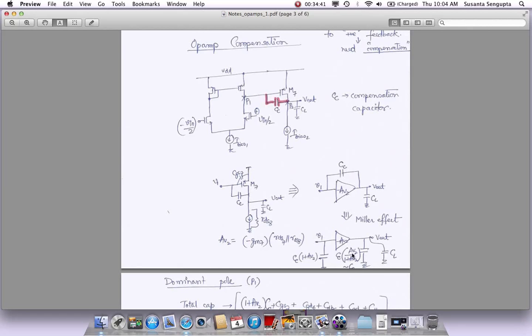CC. So what this means is, whenever you have a feedback capacitor across a gain stage where the gain is relatively high, you can break it into two capacitance components. At the input, it gets multiplied by 1 plus the gain of the circuitry. At the output, it's roughly equal to the same value Cc there.